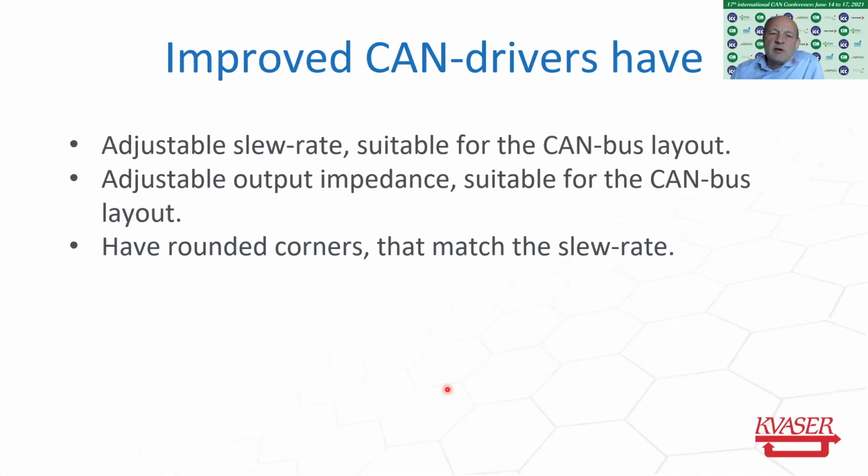I heard in a presentation, I think on Monday, that in Finland their drivers will actually have a 100 ohm impedance, which will match them better to the cable and reduce the reflection during sending, when you get feedback energy back from your drop lines.